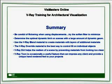The blend material should be used whenever possible to break up the tiling of materials in your scene, and it's a great feature that just adds depth and realism in general to your materials. The override material is the best way to control the bouncing of light off specific objects. Specifically, I mean the color bleed. Many times VRay generates too much color bleed, and too much can be unrealistic. This is a far better option than using the generate and receive GI options in an object's VRay properties window.